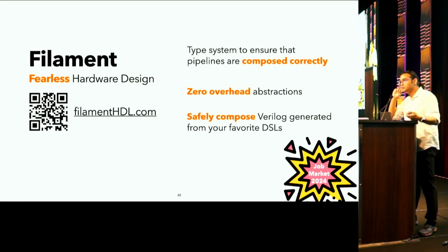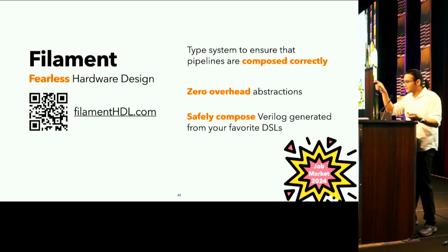I think to do it safely, it's not too hard, but it's not clear to me what the safe pipelining property means when you start clock gating. Maybe it's just trivial as you say: if this signal is asserted, turn this event stream off, and then downstream uses of that event, you can give this new clock-gated event a new name, and it can only be used in domains where that condition was true.